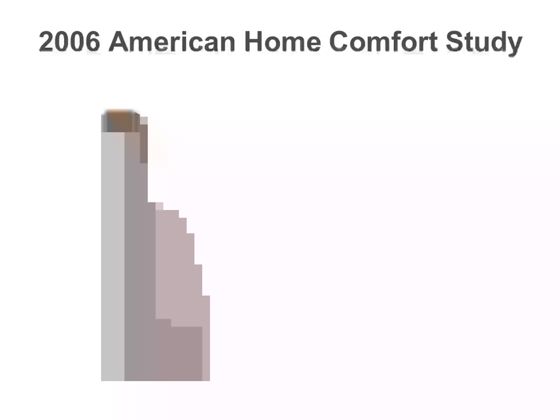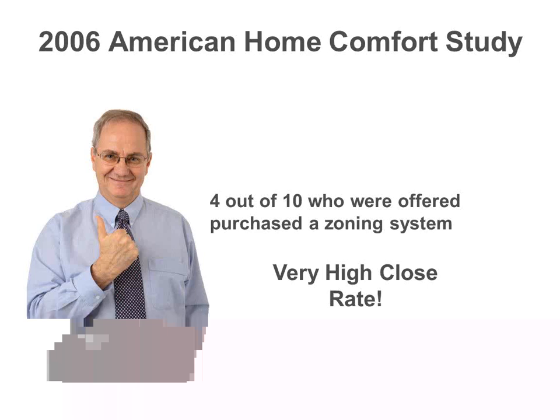You just got to offer them more thermostats to get the exact temperature they want in different spaces, and how it works behind the scenes and what ductwork you got to do. You can talk to them about that after you've already kind of explained why they want it. So most systems, when we zone them, end up being a 2-zone system, upstairs and downstairs. We certainly do plenty of systems that are 3, 4, 5, 6, 25 zones, depending on your McMansion, right? But 2 zones is very common to solve the upstairs, downstairs complaint, right?